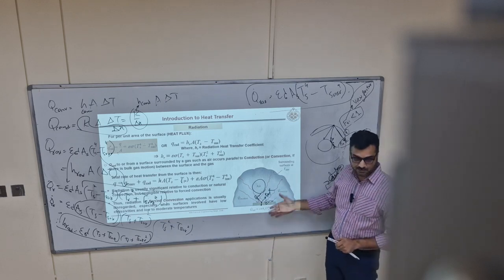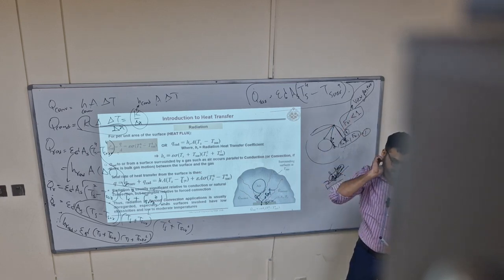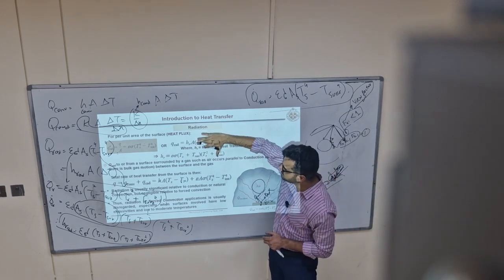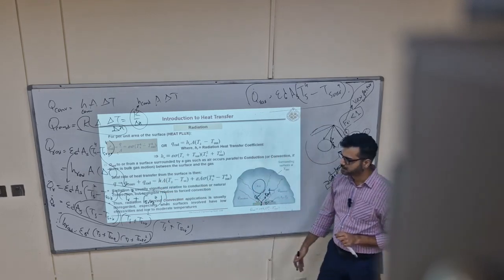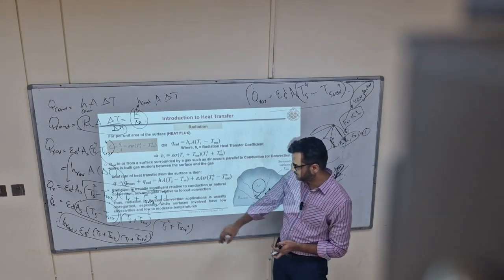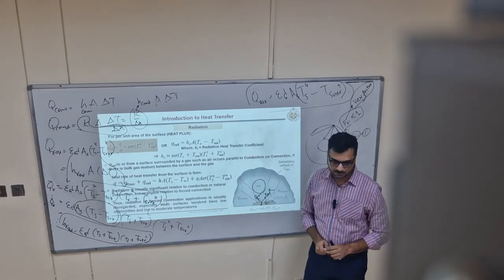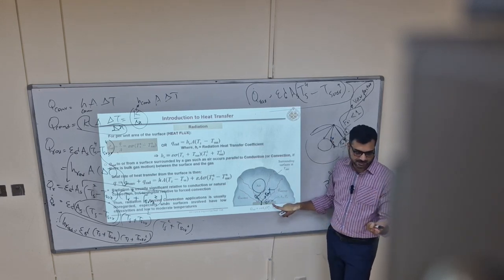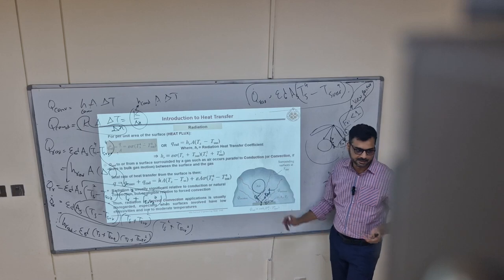We are not always solving for the sun. If there is sun, we cannot neglect radiation because the temperature is 6000 Kelvin. But for temperatures below 200 degrees Celsius, this radiation part is negligible compared to forced convection. All right, so let's solve one numerical. For forced convection, radiation can be there, but you need to check whether it is negligible or not, because normally the emissivities of those surfaces, metals, are very low, and when temperature is low, emittance is very low, so definitely radiation is negligible.